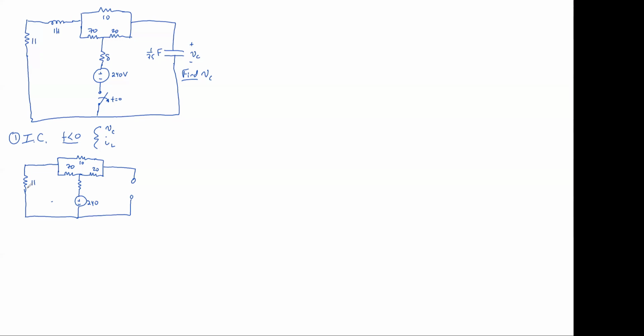Then I would define what I'm trying to find. That is perfect. And that brings us back to the fact that we haven't really defined everything we need to define in the original problem. So let's do that right now. We've got a current. Does the arrow go up or down for the capacitor? It goes down. Right, because it's got to exit more negative. And let's do the same thing for the inductor. I'm going to arbitrarily draw the arrow to the right just because that seems the way we typically draw things. I sub L, which means we've got to draw it more negative exiting and more positive entering.